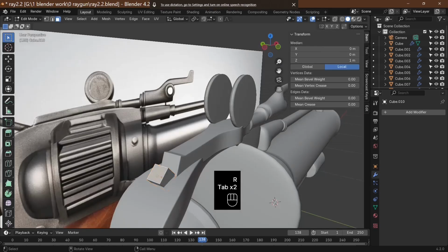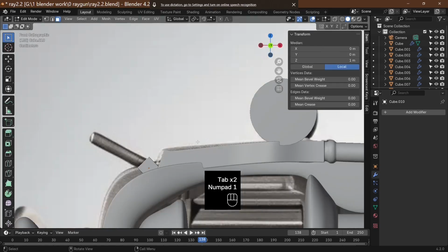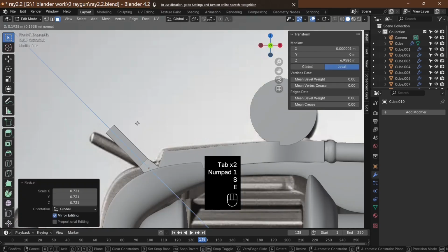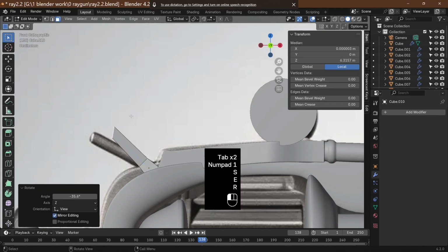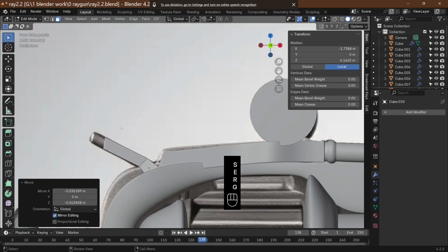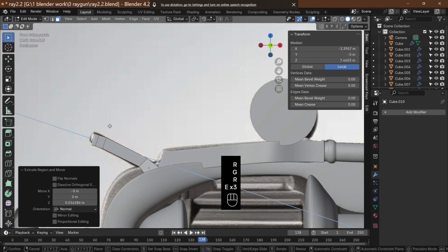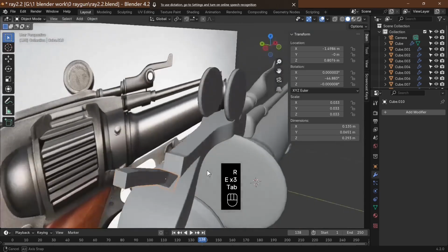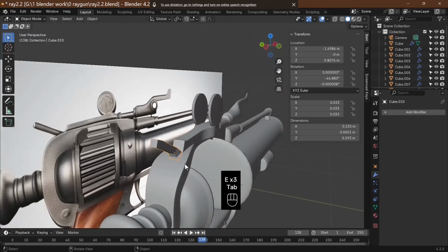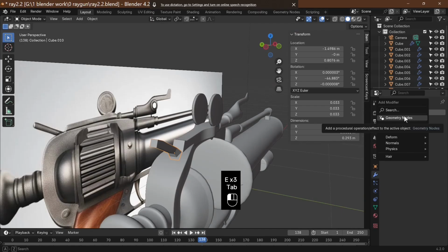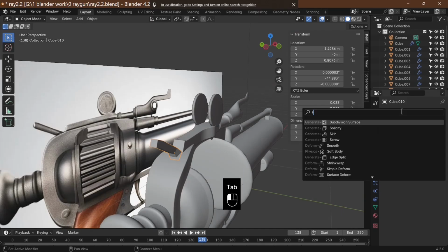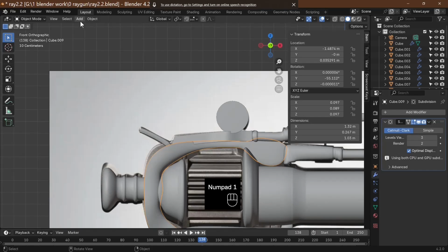So rotate. I'm just going to switch this off into edit mode. Select that face, scale it down, and just E. Rotate. G, rotate, E, E, E. Let's say it's just a little circular part, so add modifier, subdivision modifier. I haven't really got a use for it.